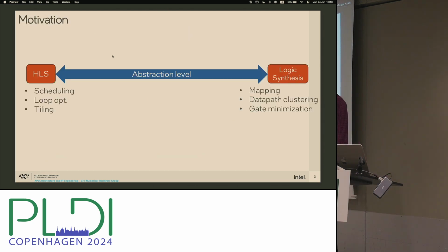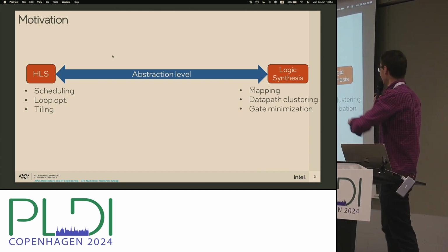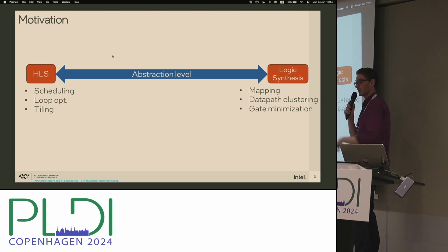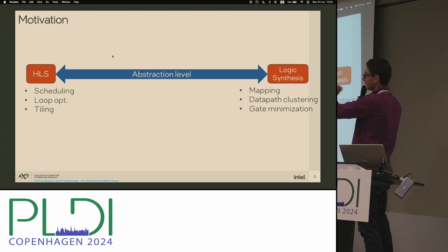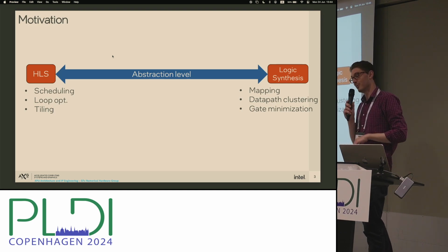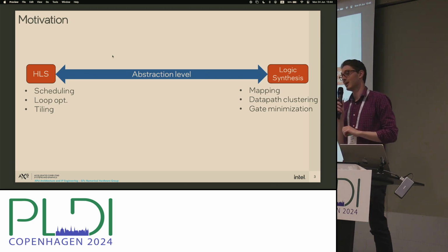And so the main motivation for most of my work has been all around this. You've kind of got this spectrum. You've got your logic synthesis tools, which are taking languages like Verilog and actually converting them into netlists. And they do these really low-level things like figuring out that a plus should be turned into a bunch of AND gates and OR gates. And they do these kind of clever techniques on gate-level stuff.